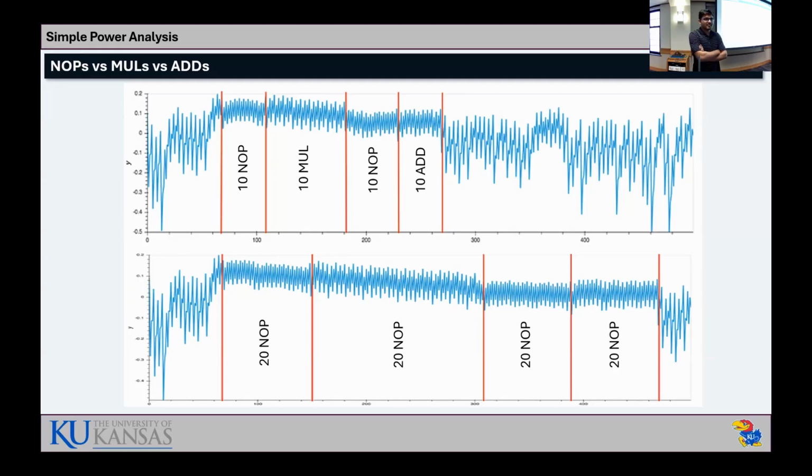Have your system emit fake traces? Yeah, randomization. If you add more noise here, random noise, what will happen? Otherwise you will always have this trace. But with noise, the attacker will not know which kind of operation it is doing, because you are getting the power from the whole CPU, the whole processor.